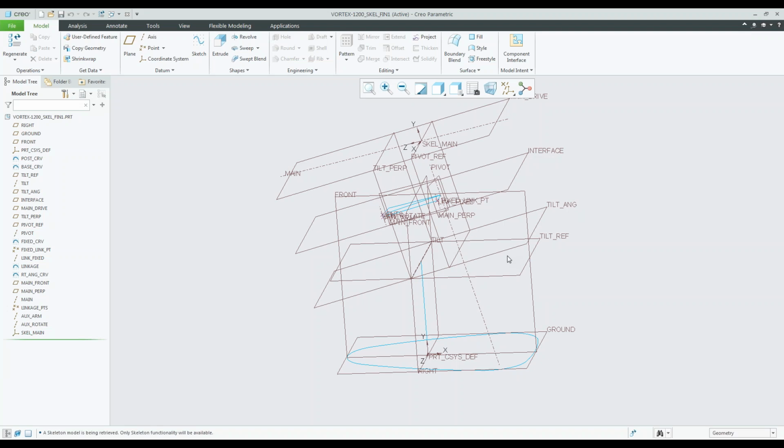Now, it's not limited to just sketches and datum references. You can also include items like space claims, or once again, motion, or critical interfaces. So let's do an example where I'm going to start creating some space claims for our fan itself. And we're going to take a look at the base unit first. So if I wanted to create some space claim information with the base itself, I'm doing this all within the skeleton model still.